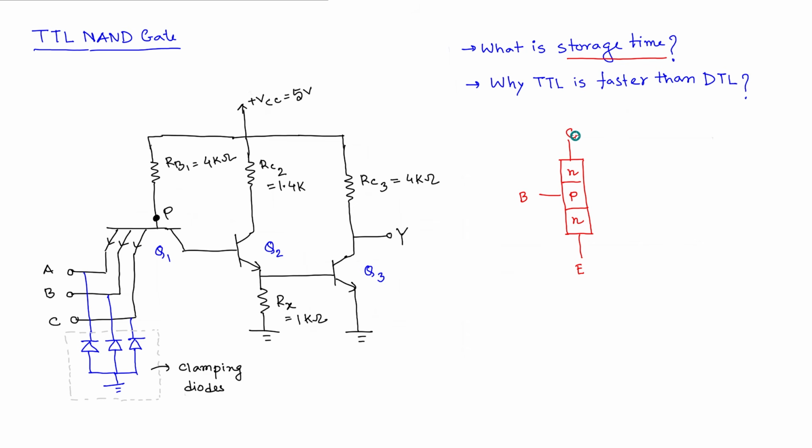Whenever we say this transistor is in saturation, that means a high amount of current is flowing from collector to emitter, or if I take the convention of electrons, the direction is from bottom to top. A high amount of electrons is flowing from emitter to base, then to collector. These electrons are majority carriers in the N region, and also in the N region of the collector, but minority carriers in the base. And this is a hostile environment for those electrons because they are minority carriers there.